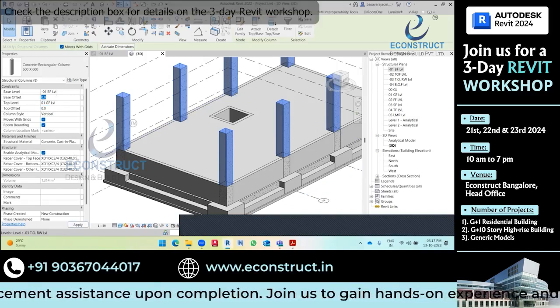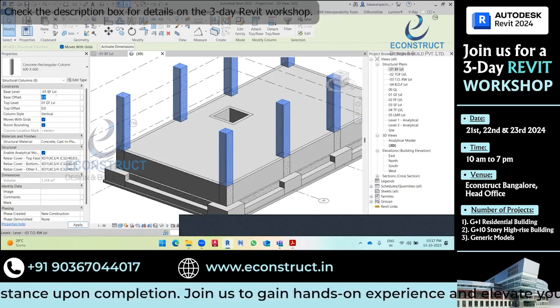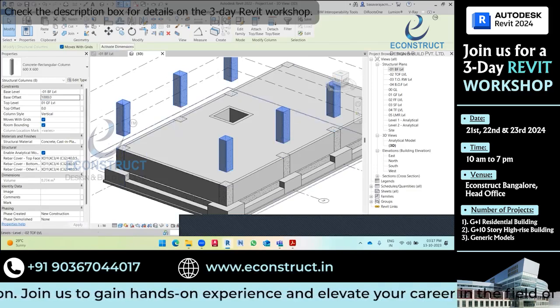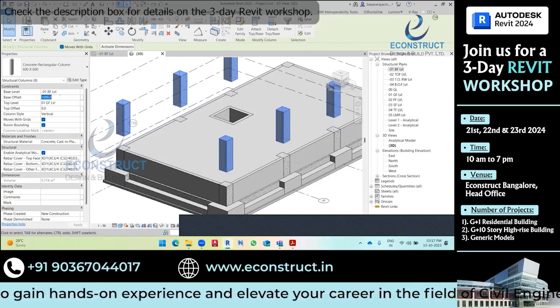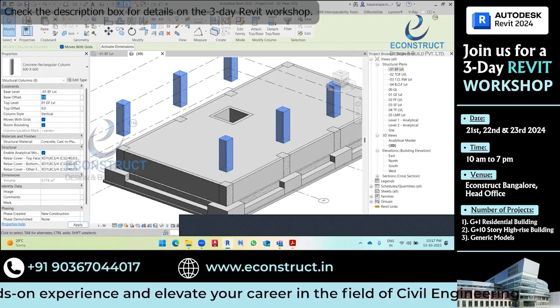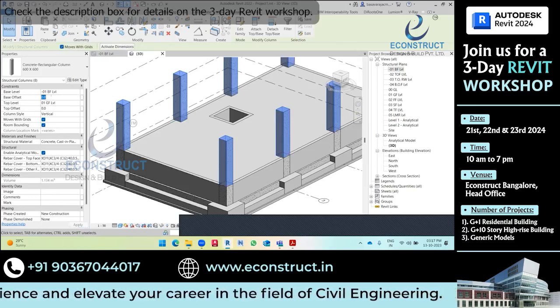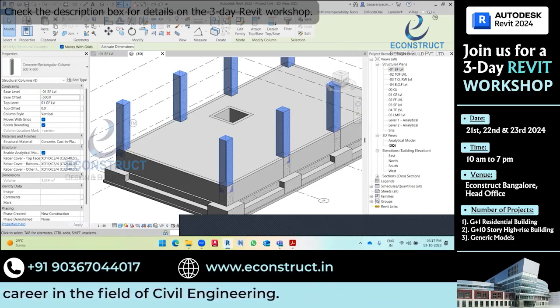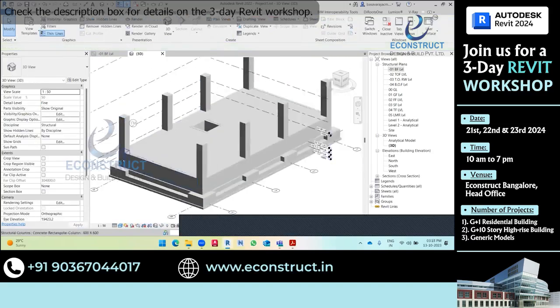And if you want a base offset, you can give the base offset also. For example, I will give 1 meter, and the base offset will be applied. Or else you can give a negative offset also. If you give a negative offset, say -500, it will go below that level. If you give positive values, it will go above that level. Now I don't want any offsets, so I will make it 0 and click OK, apply.